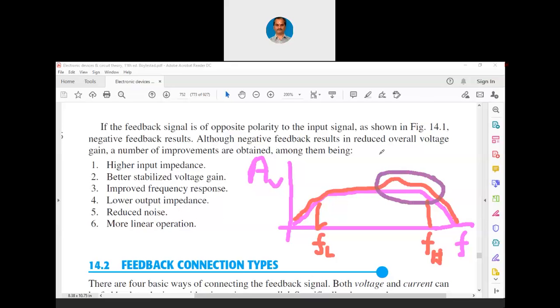Now, you may wonder why the gain is not uniform. Here, you can see the frequency which is in the increasing order. The device may not have flat response for these frequencies now, because we don't know the circuit parasitics. We had seen all these things in the previous module about high frequency analysis, what all other parasitic components are coming into picture.